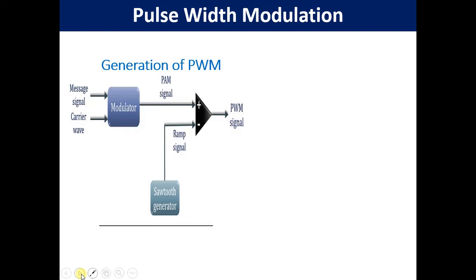It is a type of pulse time modulation where the timing of the carrier pulse is varied according to the modulating signal. Due to the constant amplitude property, it gets less affected by noise.